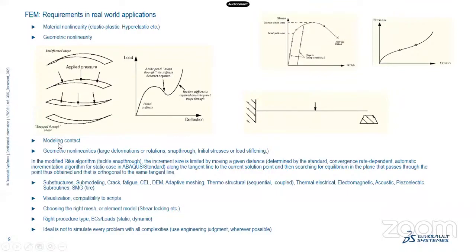The third one, a major component, is modeling contact. You see here, it's a cantilever beam. If this is not there, it's a simple linear cantilever analysis. But once you have a contact, it's a different problem, and that will introduce nonlinearity. There are different methods to model contact in almost all the software. It's a kind of constraint optimization, and can be Lagrange multiplier or penalty based methods.